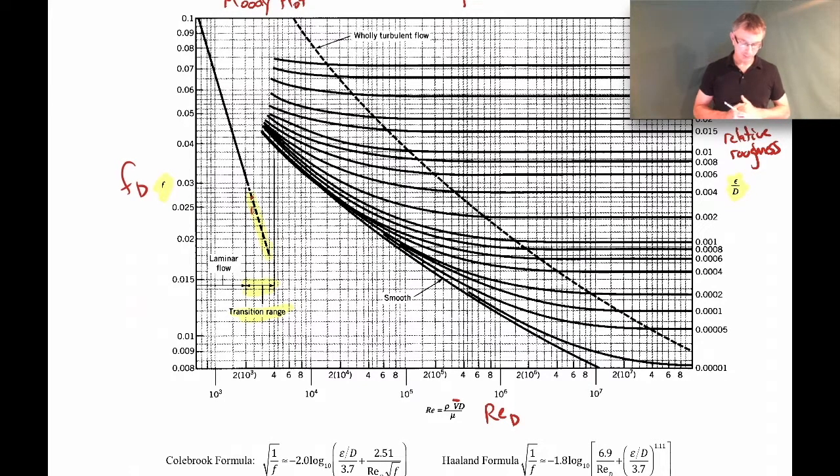There, we don't actually have a really good value for the friction factor. And the reason for that is because we're starting to transition from laminar flow into turbulent flow, which is over on this side. Right? So the laminar flow ends at about, let me put this in red, about 2300. And then here we've got the turbulent stuff occurring closer to a Reynolds number of 4000.